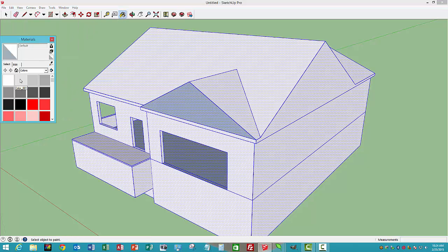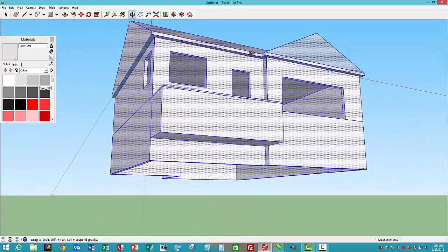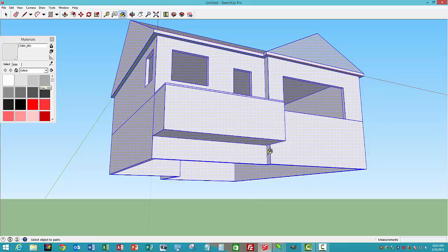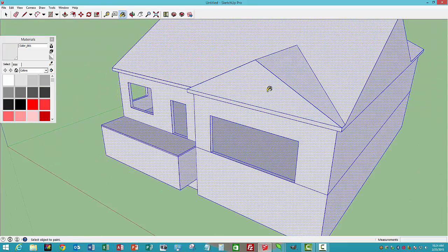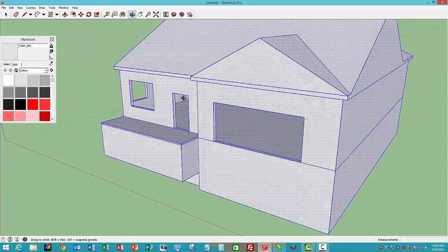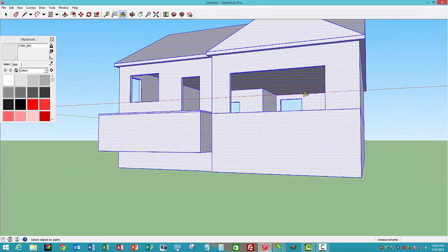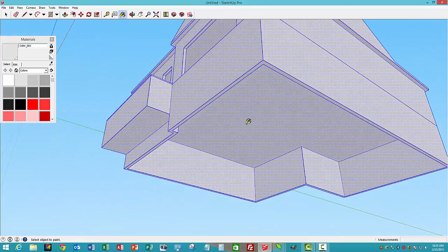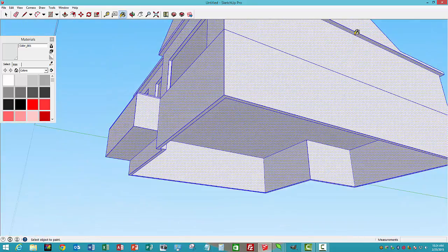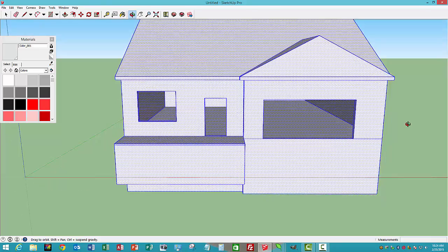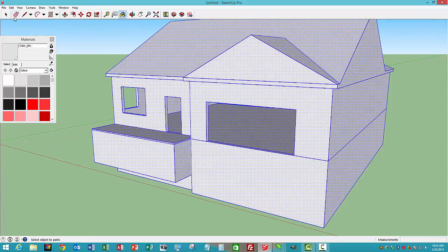This next step's kind of important because you want to take the fill tool. I've got everything selected, and then make sure everything is painted with a color. Everything. Interior walls, floors, ceilings, everything. And then you'll come in later and create your textures, but this way you'll be able to go in the home. The wall will be a solid surface, and you'll be able to look out those windows without having anything going kind of funny or funky on the system. So make sure everything is colored in.